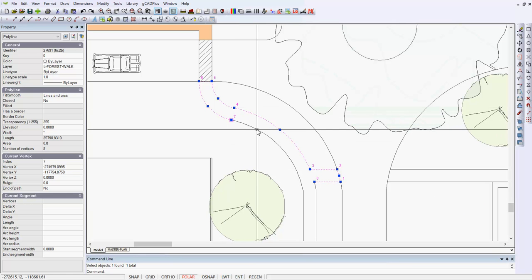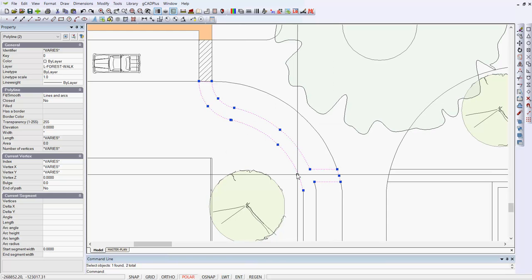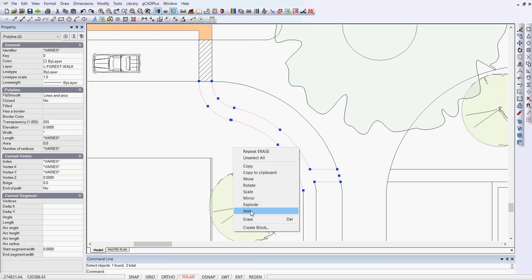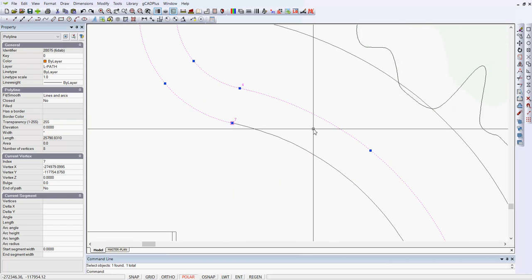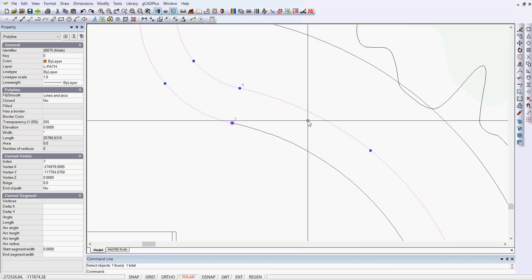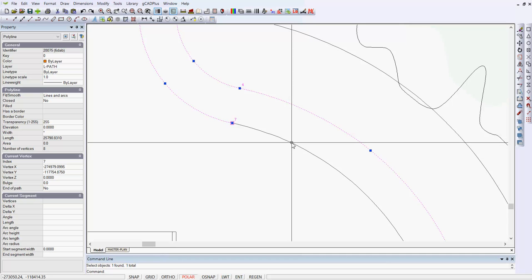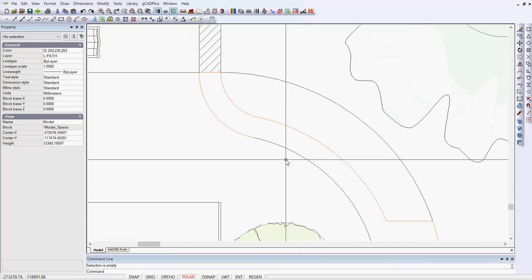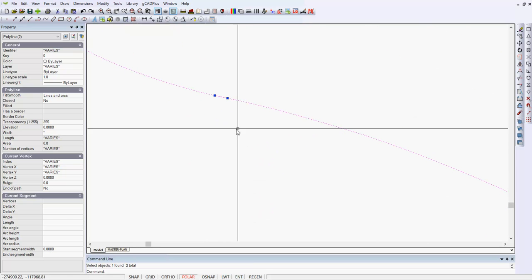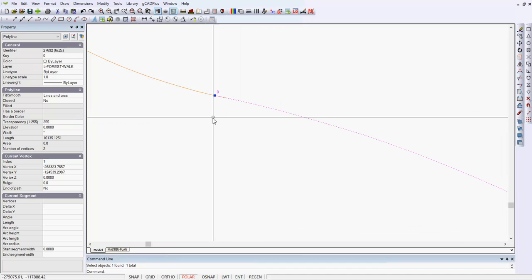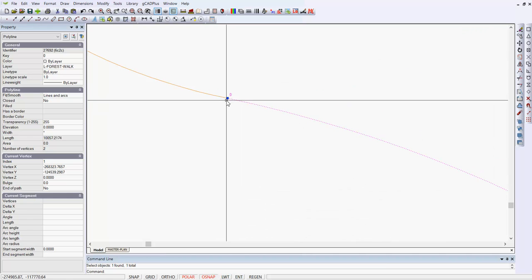We can attempt it. I've selected it, so I want to make a polyline around that area there, and if I say join, then you see that although this polyline has moved to my current layer, which is called L path, this second polyline segment, or was it an arc? No, it was a polyline, did not join. And the reason it didn't join, we've alluded to before. If we pick both of these, then you see the endpoints are not congruent. So we need to move the endpoint of this one, so I can pick it, and we need to move it to the endpoint of the other one.